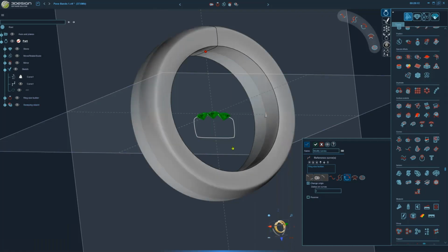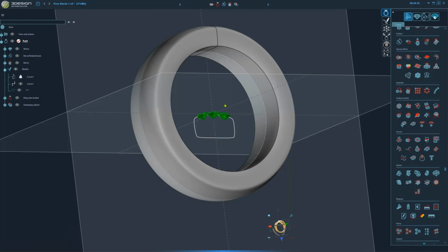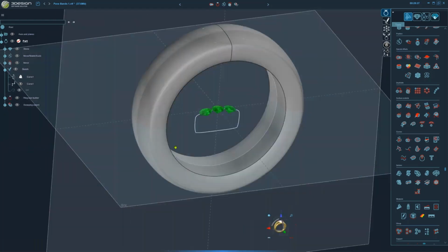So I'm not going to do that now because I want to keep it just based on the original top one here. But keep that in mind too. If you want to change the start point, you can do it here with this modify tool. That way you don't have to mess up your curves in your sketch. Your sketch stays basic, simple. You do it here. This is going to give you a copy of the curve. Use that to sweep around instead of the original. So that's another way we can control it.